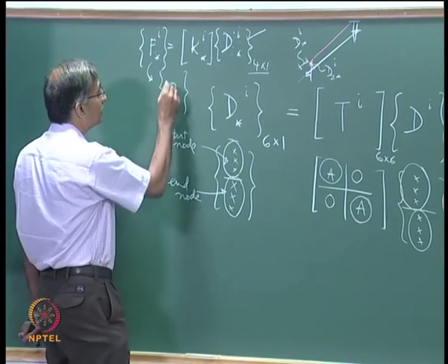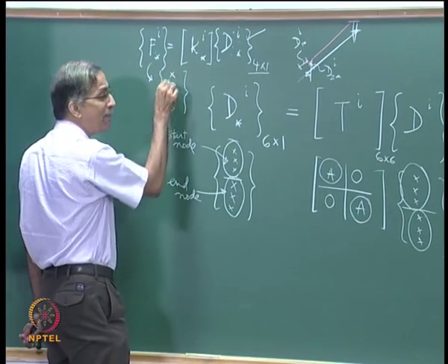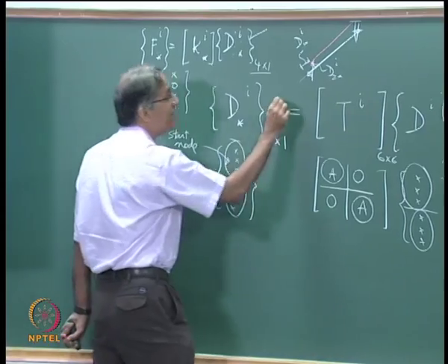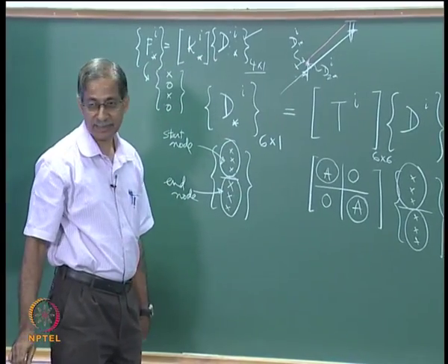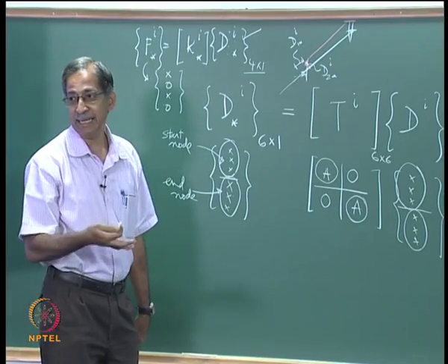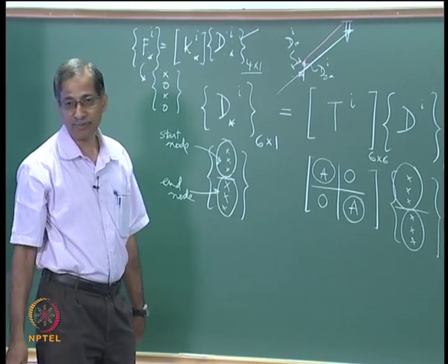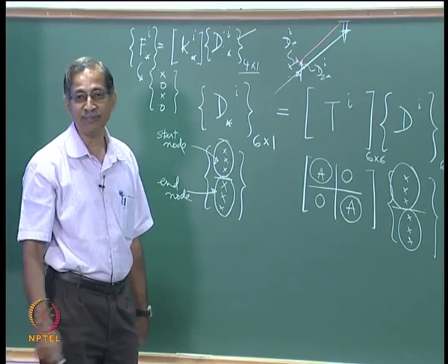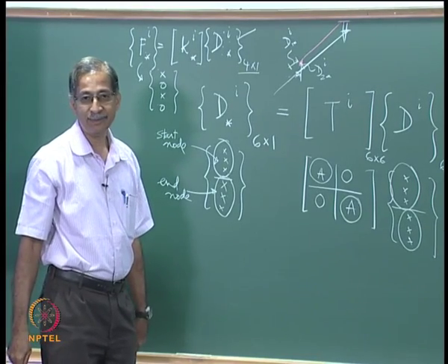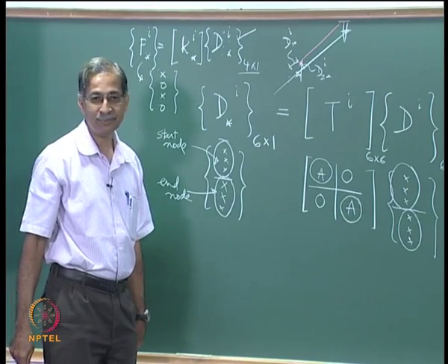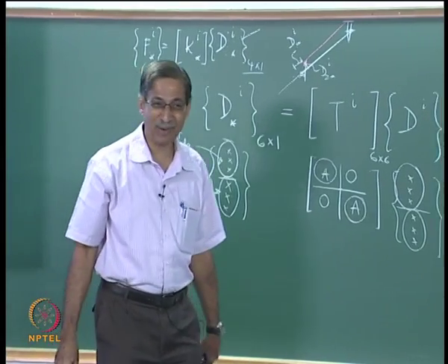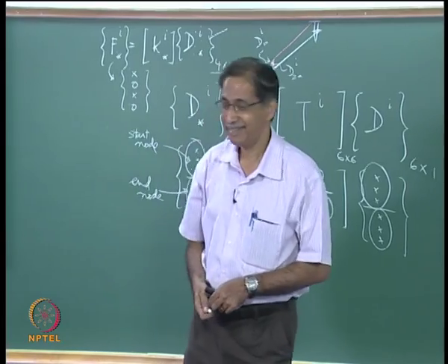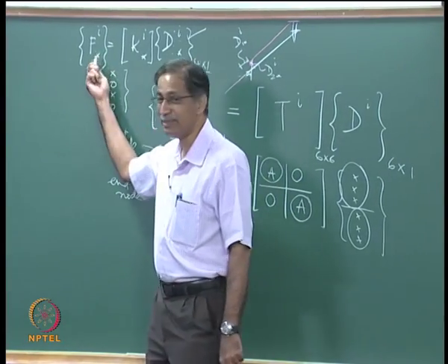And even worse, these 2 are not truly independent because the resultant of them must be aligned along this direction. Is it clear? So we will see it is related to the rank of the matrix. What is the rank of the stiffness matrix? It's 1. So that you can see that this can be reduced to 1.